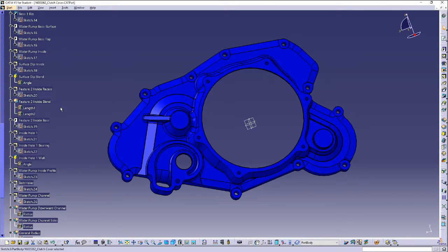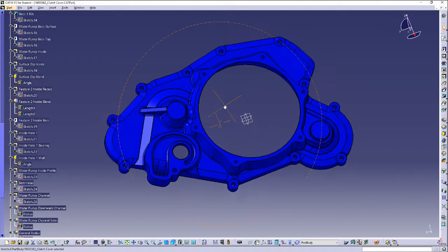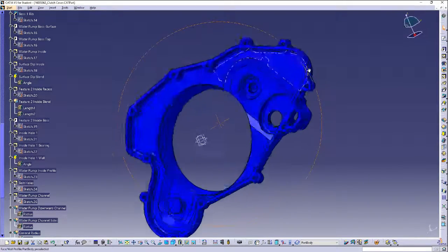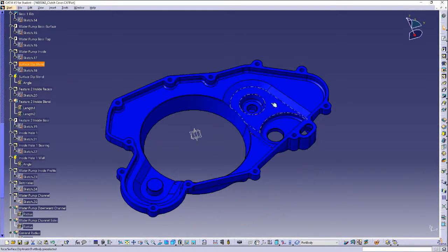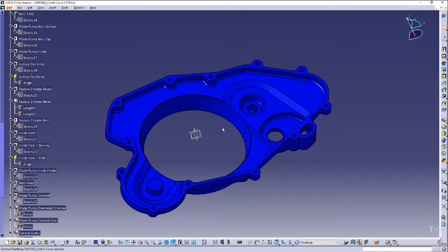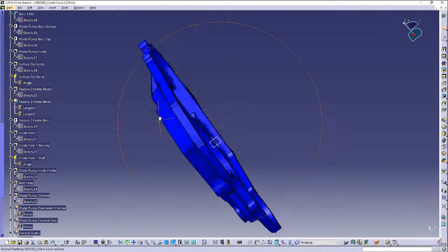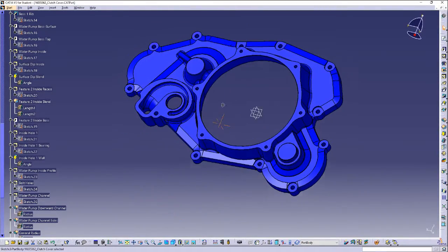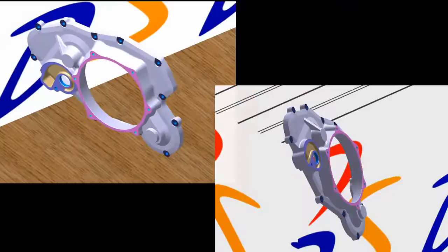The order was done in such a way as to get the main shape and profile first and the surface, and then to work from the surface upwards to produce the outside face, all of these features. And then once that was done, the inside face features and surfaces were all worked on. Once this was done on the inside, all of the fillets over the entire part were made. This is to make sure none of the features break.